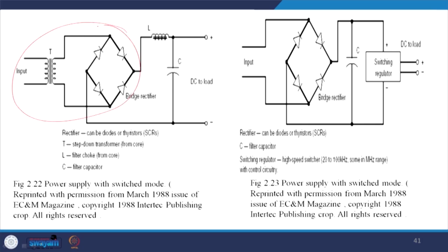So, this is the normal rectification, and thereafter you will have a ripple DC here, and after the filter you have a constant DC here. Since it requires a bulky 50 hertz transformer, we try to get rid of it and instead have an SMPS. This normal rectification is what we generally use in our project work, a 220 volt to 18 volt supply, something like that. Instead, we prefer SMPS.